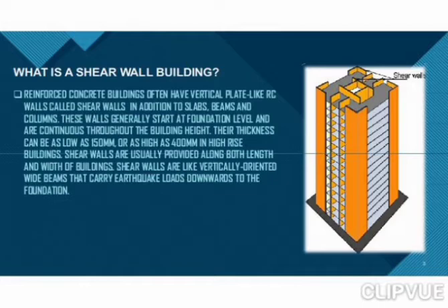Shear walls are usually provided along both the length and width of buildings. Shear walls are like vertically oriented wide beams that carry earthquake loads downwards to the foundation. So in the figure we can see a building indicating the shear wall.